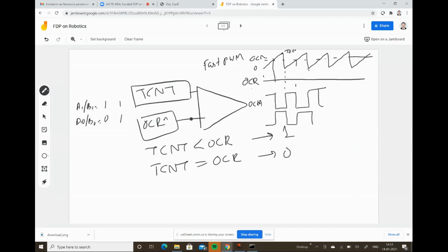So if I store this value, let us take an example, 0x02FF. This is a 16-bit register for timer 1. Okay, so even if I store this value, the maximum value is only 0x0FF, and there is no condition where the values of these two registers will be matched. Okay, so that should be taken care of.